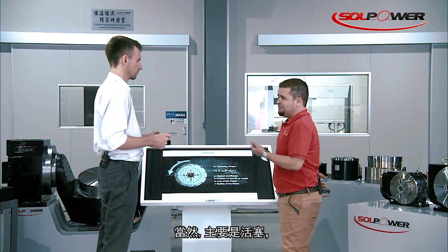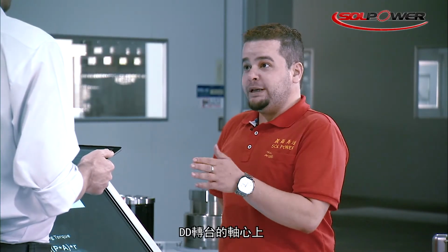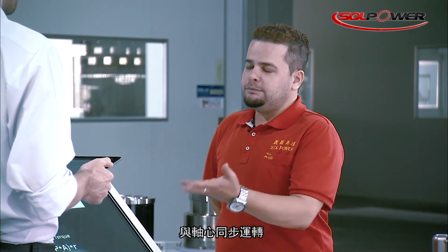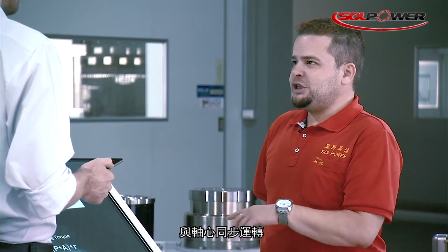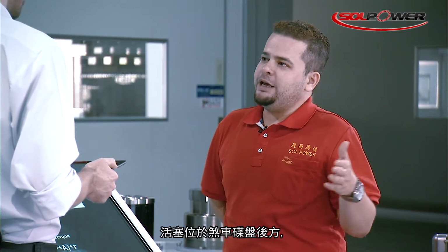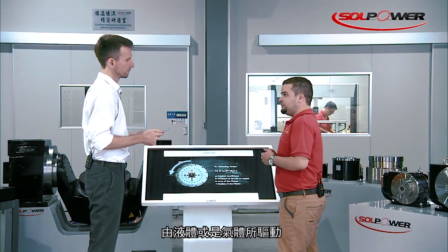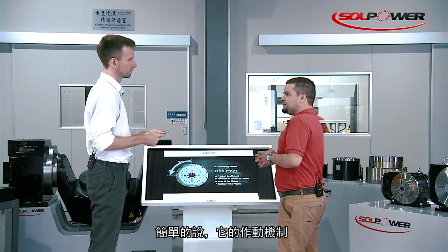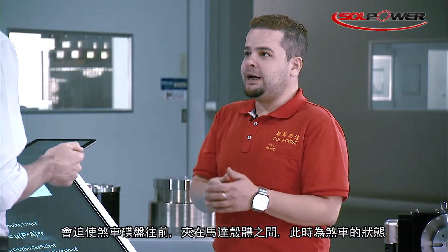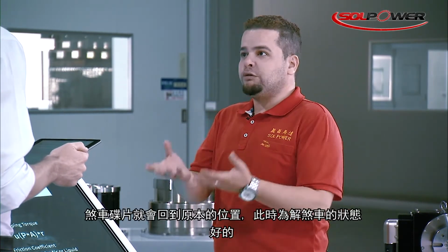Obviously the piston and the liner. The liner is fixed. We assemble it fixed on the DD rotary table shaft, and it turns synchronously with the shaft. The piston is located behind the liner, and the piston is driven by either liquid or air. The mechanism, in simple words, is that when the piston moves forward, it forces the liner to climb up on the motor. And when it moves backward, it releases the clamp.